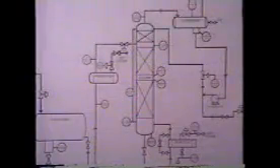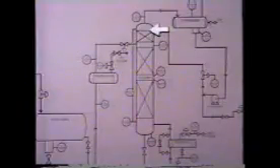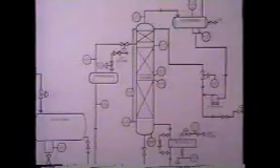The same thing can happen if a tray or a part of a tray breaks loose and falls onto the tray below. In columns that use packing instead of trays, the packing itself may become damaged and restrict the flow of vapors or liquid. Reducing the amount of liquid going back to the column will help to control the flooding caused by these mechanical problems. Eventually, however, the column will have to be shut down so that the problem can be repaired.